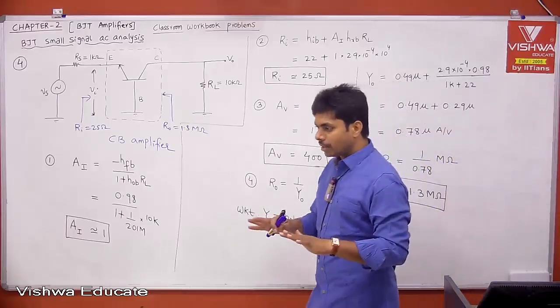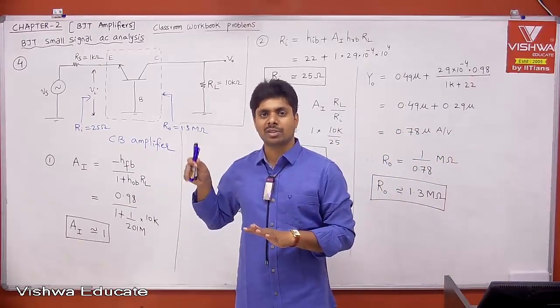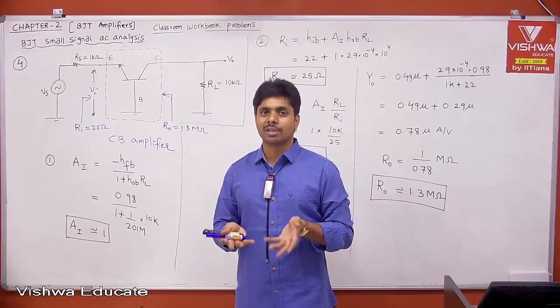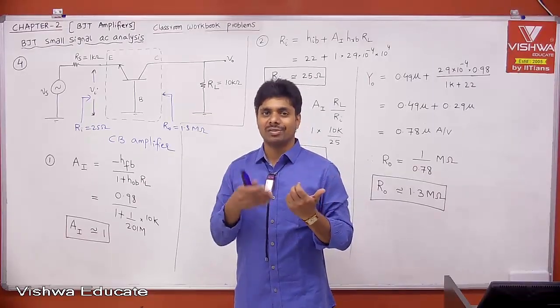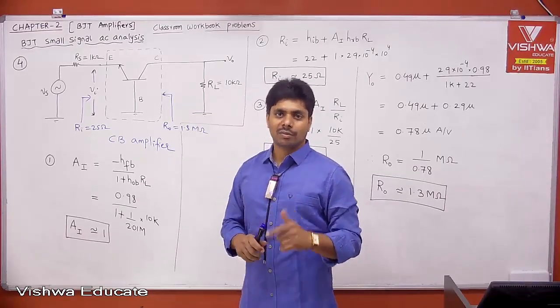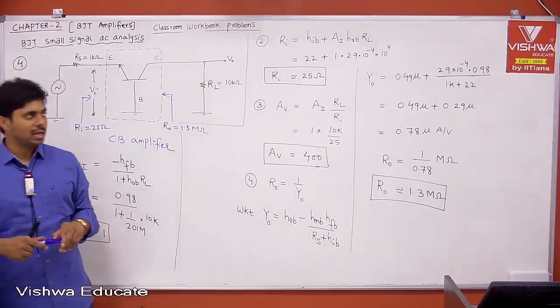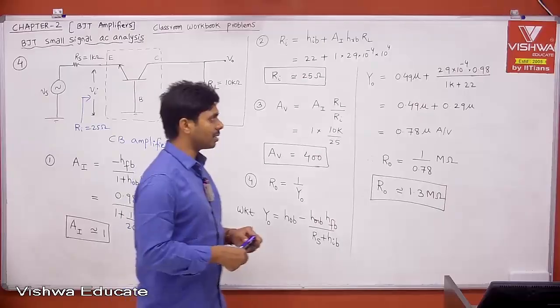Typically, if you say buffer amplifier, the default is voltage buffer, no need to specify voltage buffer amplifier. But here it is a current buffer amplifier because it is doing buffer action for current. Specifically, we need to specify. Therefore, the common base amplifier is also called a current buffer amplifier.